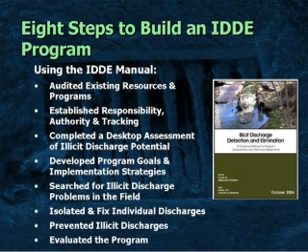A couple things to mention here, particularly the third one down, this desktop assessment of illicit discharge potential. As I mentioned, every community is going to be different, with different ages of infrastructure and different kinds of problems going on. So what we want you to do is look at your sub-watersheds and do an initial screening assessment so you have an idea of particular areas that might be hot spots and others that are maybe of lesser priority. Then as you go out into the field and look for illicit discharges, you can continually update that assessment so you build over time a better sense of where your real problems are, and what kinds of problems you're experiencing.